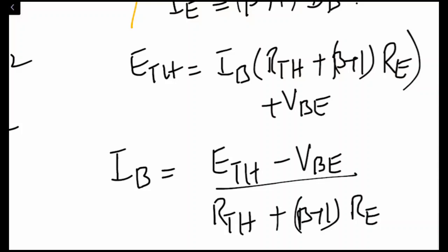Okay. If you see, initially what I said, the voltage divider circuits have more stability as compared to circuits where we do not have the emitter resistance. When we were doing the first circuit, the biased base, the fixed bias configuration circuit, we did not have any resistance in the emitter leg, right?